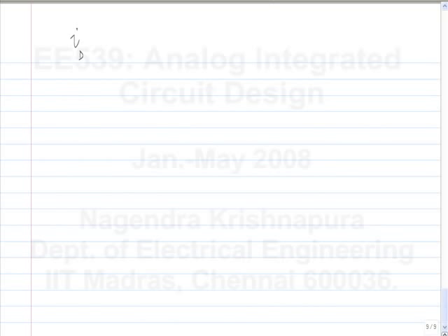And you can do this for any device, right? This has nothing to do with a particular nature of a MOSFET. Any device in which some quantity is nonlinearly related to all other quantities, let's say the cause and effect are nonlinearly related, you expand it in a series and you throw out everything other than the first order term and you come up with the small signal model. Okay. And you, I think, are already familiar with the small signal models of a diode and a bipolar transistor and MOS transistor and so on.